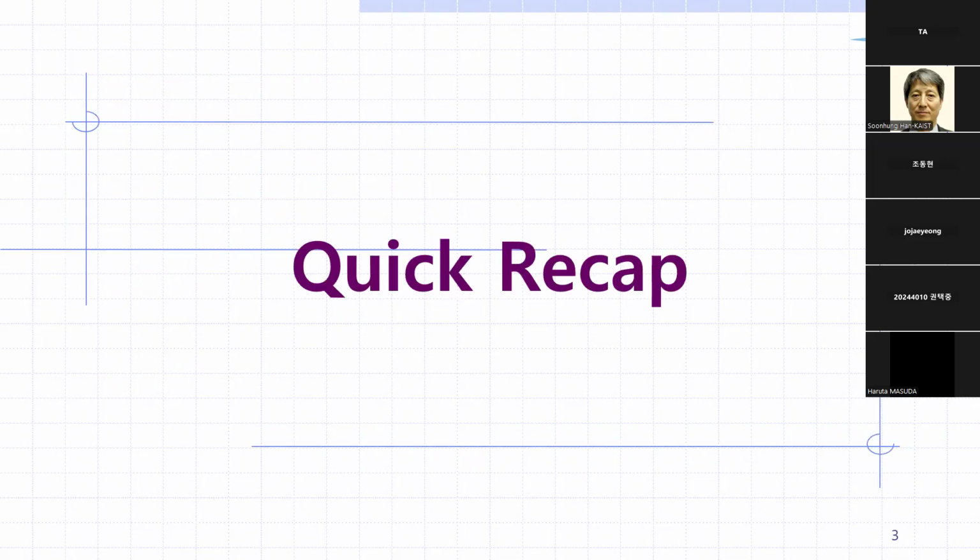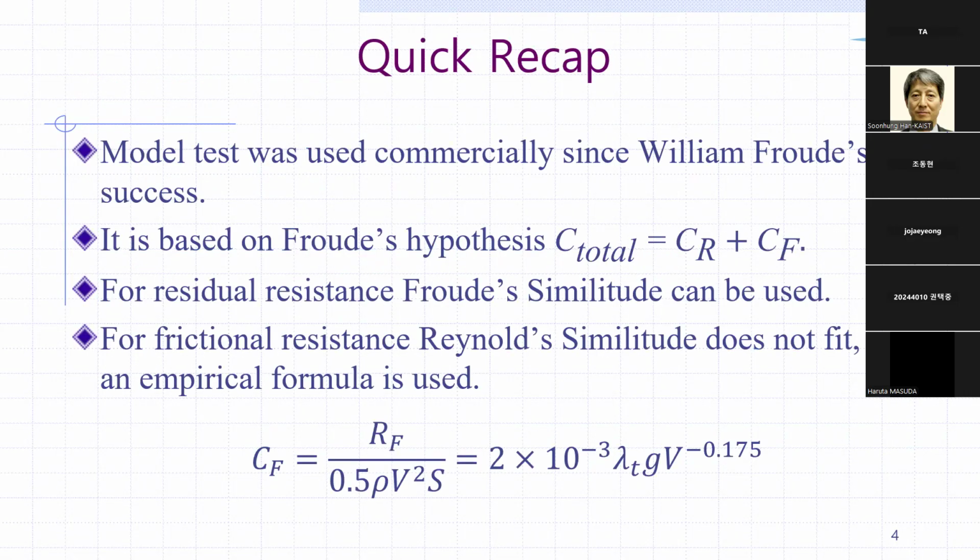So, a quick recap of what we studied about model tests. The model test has been used commercially since William Froude's success. It is based on Froude's hypothesis that the total resistance is the sum of residual resistance and frictional resistance. For residual resistance, Froude's similitude can be used, but for frictional resistance, Reynolds similitude does not fit.